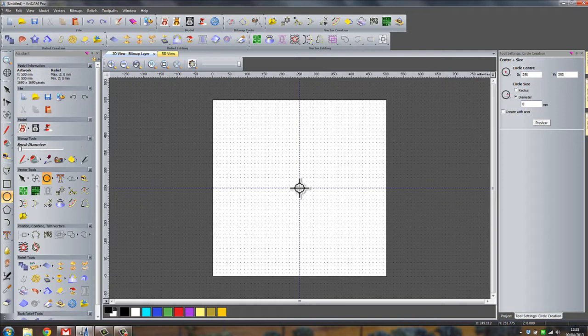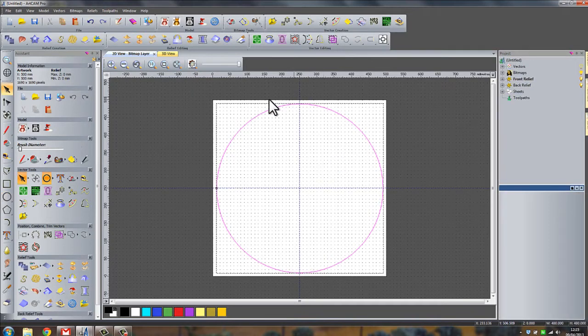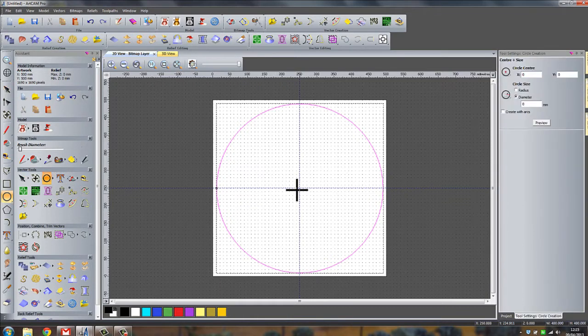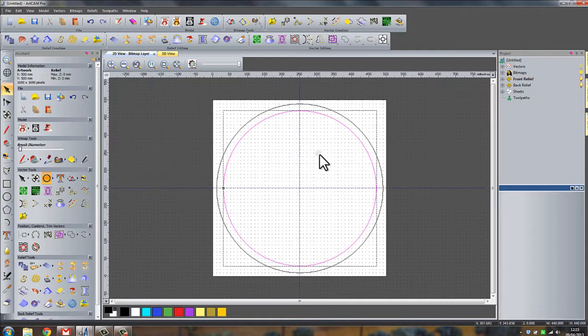If I drag a shape and pull out, I can change the diameter, and I want to change that to 480mm. Click on Preview and right hand click, and that then will be formed. And I'm going to do that again for 2 further circles. Click in the centre, drag out and release, change the diameter to 440mm and release, right hand click.